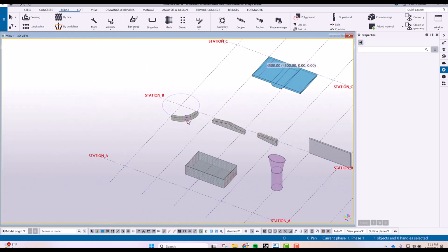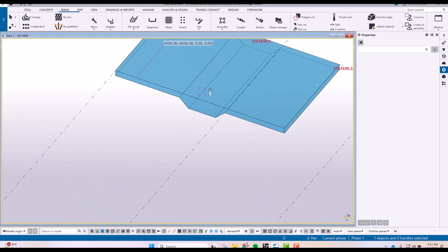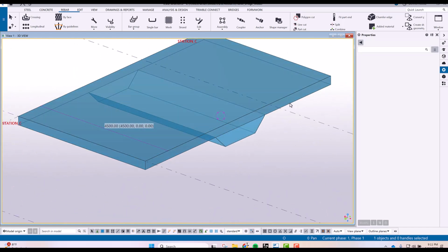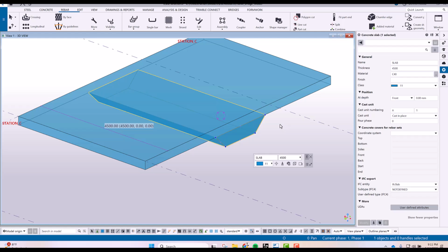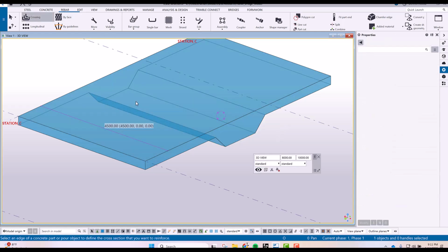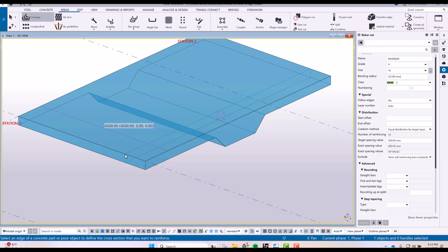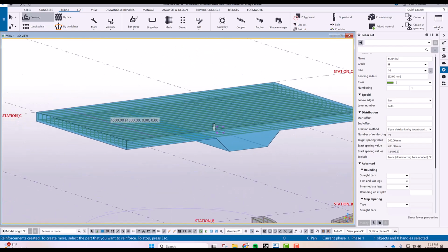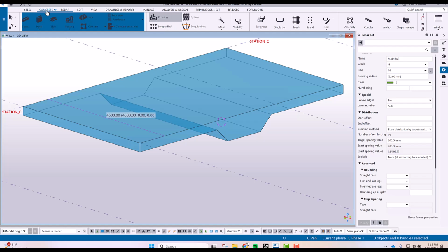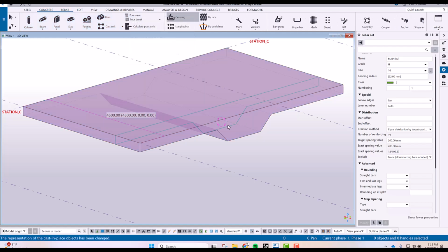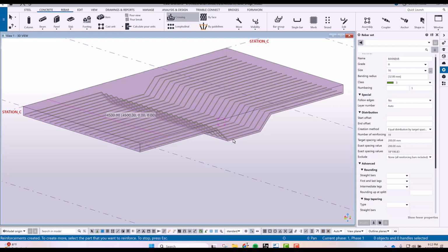All right. And also, if you have this kind of situation, if you notice here in Tekla, this one is made of cast in place, but basically these are 2 parts. So if I click the crossing here, you will notice that it's only showing the slab like this, right? But if you want to make this one as one entity, all you have to do is change the pour view. So look, now the shape is different. If I click here from this part, shift key to this part, middle button of your mouse, then as you can see here,